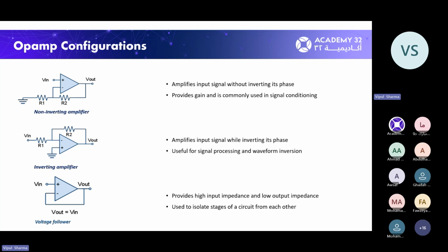By buffer, I mean if you want to drive a very high drive load kind of element in your design, it can introduce a loading on the preceding circuit which is driving that load. So in between you can introduce an op-amp. The op-amp will have a gain of only 1, but it will have sufficient drive current through its second stage, that is a common source amplifier, and there will be no loading effect on the signal being driven through this op-amp while driving a further high drive load, which is followed by this source follower circuit or buffer circuit.